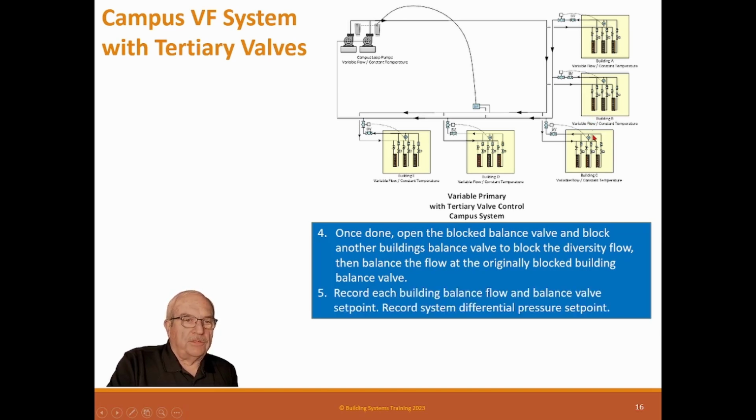Record the building balance flow and balance valve set point. Record the system differential pressure set point. So your job is, if you're just doing one building, then you'll set up this building, set this set point where it needs to be. But you may have to reset the system pressure set point if you need more pressure to run this whole system.